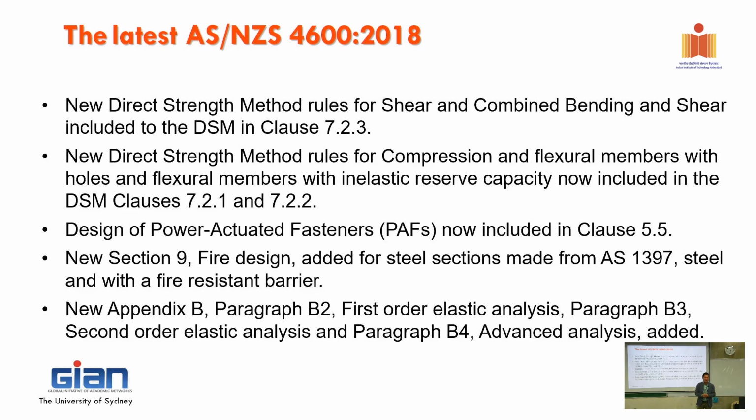What happens now in any standard is that you have to run a structural analysis, right? And then you break it down into column, beam, or whatever component and design for that. So that is member based, and all the rules in here are based on the member. You separate into column, beam, shear, and everything, and then you design for that. However, the advanced analysis allows you to design for the whole system. You can build the whole portal frame or the steel structural frame and run FE analysis, and you get to design for the whole system without having to check any single member.